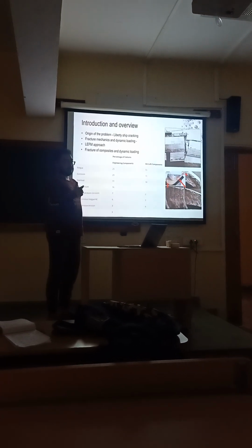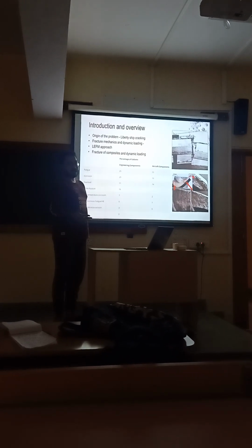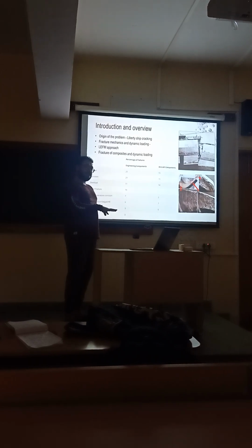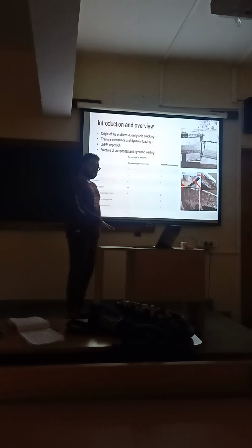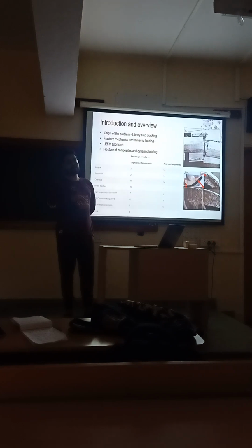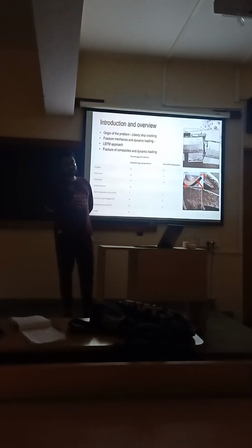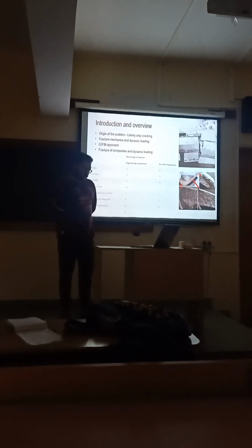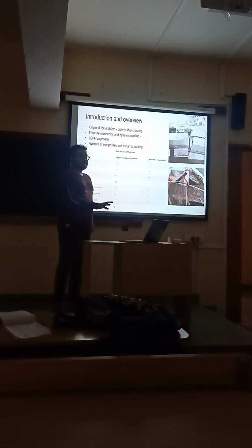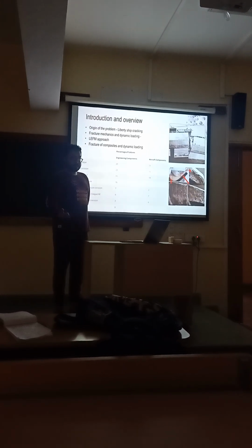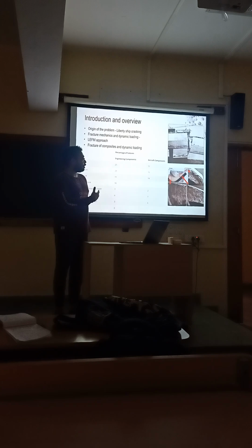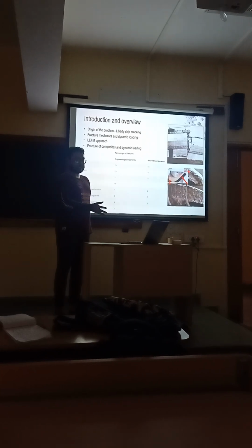After that, a benchmark shift happened in structural dynamics and fracture mechanics. In 1921, Griffith proposed his critical energy theorem, which says that for any material there is a critical energy. If you supply energy more than that critical energy, a crack should propagate. And there were no assumptions or anything like that. Looking at this phenomenon, we have to shift from that theory, because dynamic loading can cause this kind of devastating failure. This was the first example of that.